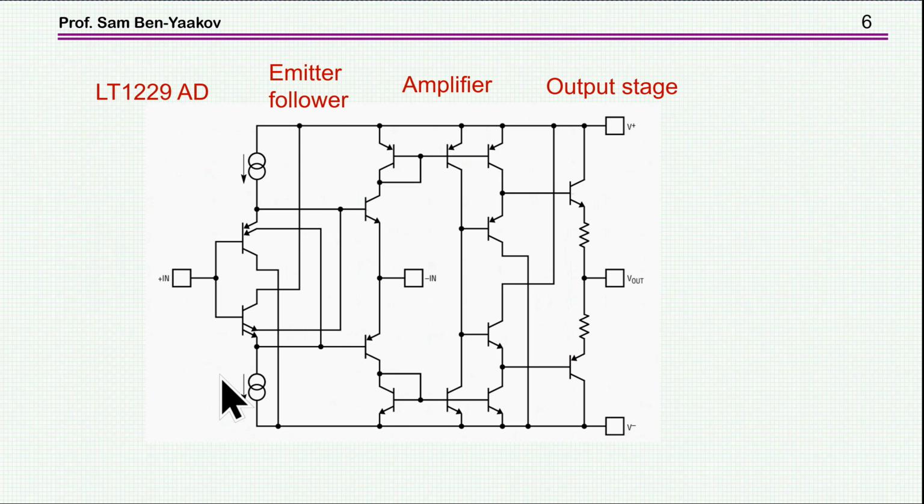And here is a simplified description of a CFA, by Analog Devices, this particular unit. We have here the unity gain amplifier between, say, this PNP transistor and this NPN transistor. We enter here, and the output actually is here. The reason for having two transistors is to subtract the base-to-emitter DC voltage. So we start with a DC level here and end up with about the same DC level here. The gain, however, is 1, because it is actually two cascaded emitter followers.